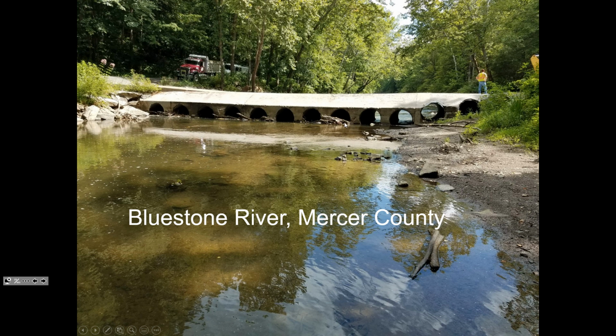There's lots of branches and trash that gets thrown into creeks and rivers. And if it's smaller than the diameter of that barrel, it can get lodged upstream, and it could create a damming effect, and it may need to flow over the top. That's something that we're going to talk about today when we get into the HY-8 program, is overtopping.